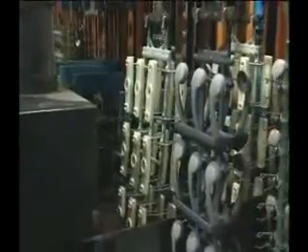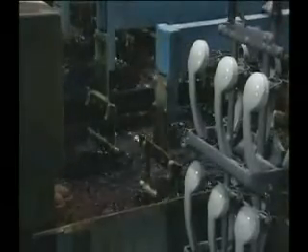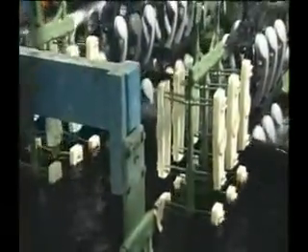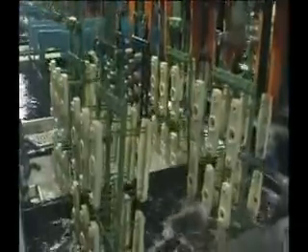Plastic parts are prepared for electroless plating by submersion in a sulfuric chromic acid bath. This acid slightly etches the plastic substrate surface, creating microscopic pockets or pockmarks. After etching, the plastic parts are placed in an activator bath and an accelerator bath.